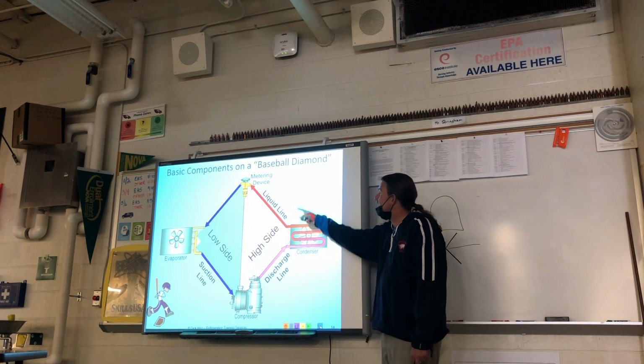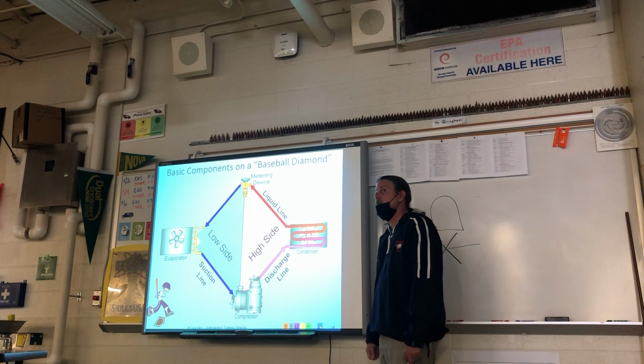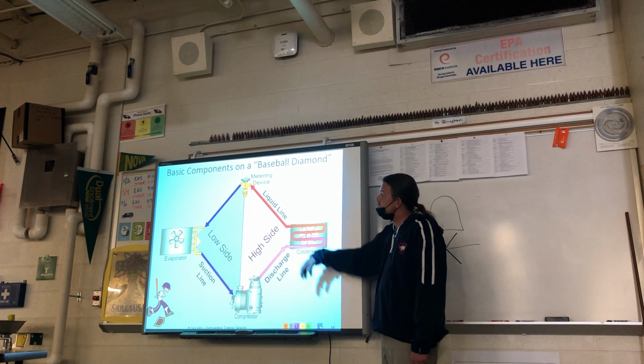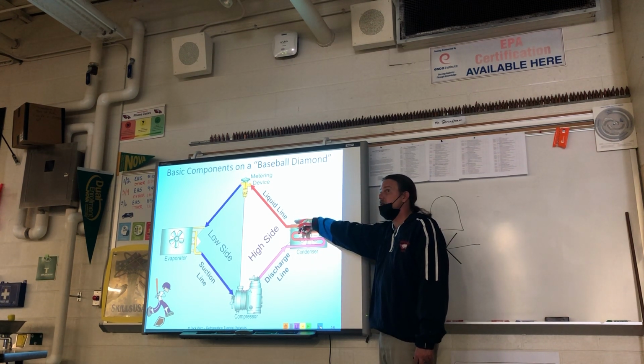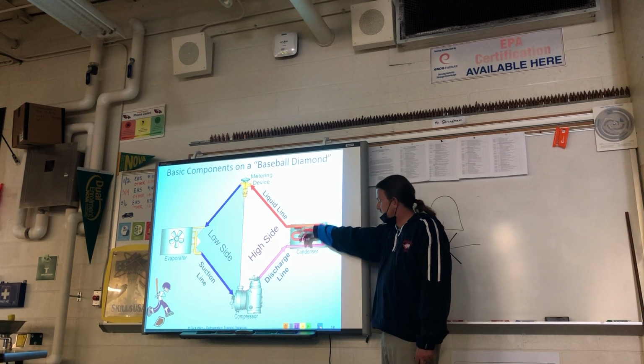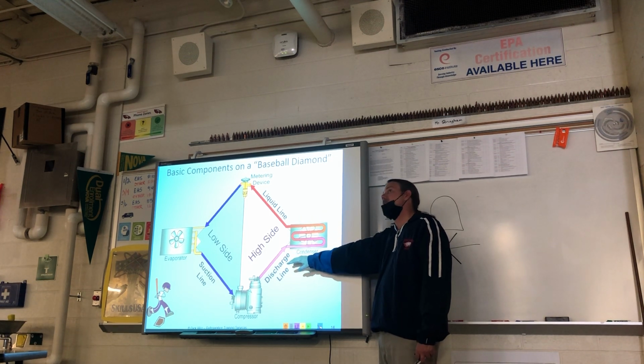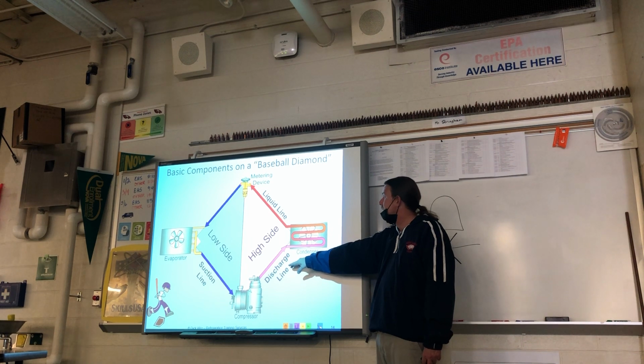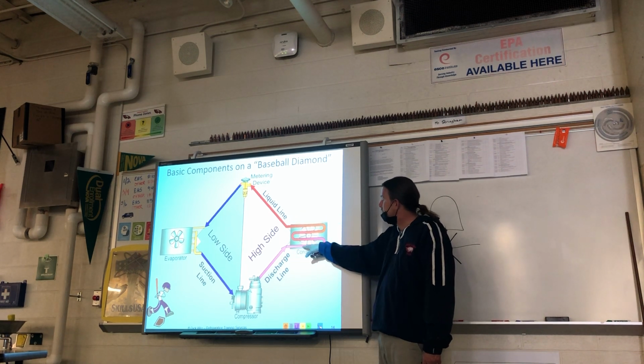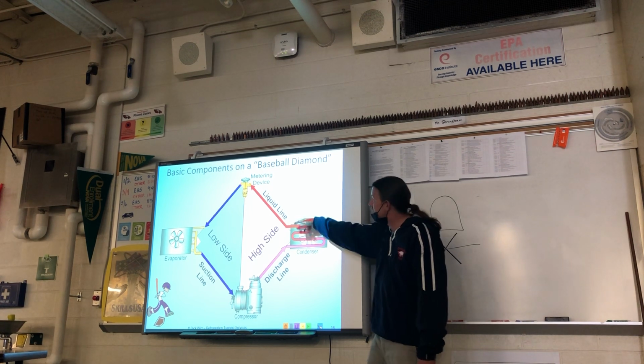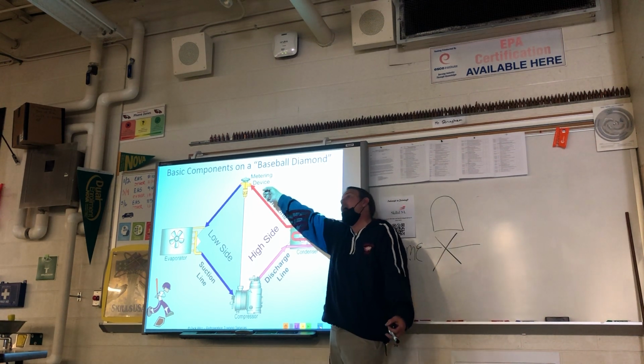Yes, but which one? Because I got two lines on the high side. Liquid line? Okay, the liquid line is going to be the hottest. Oh, the discharge. The discharge, because it's the hot gas that's superheated coming out. And the liquid line is after it goes through the de-superheating, the condensing, and the subcooling. So it should be about 95 degrees, which would be hot.